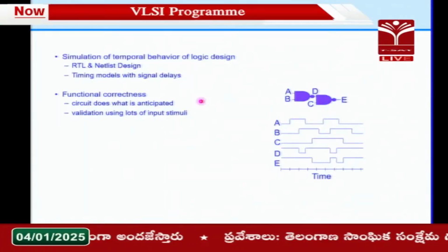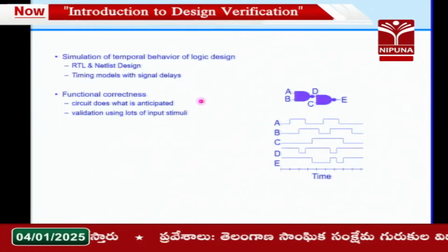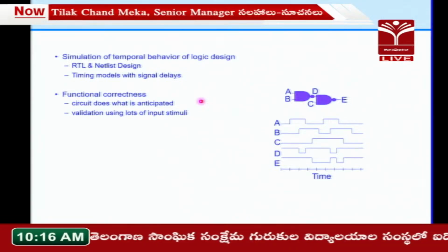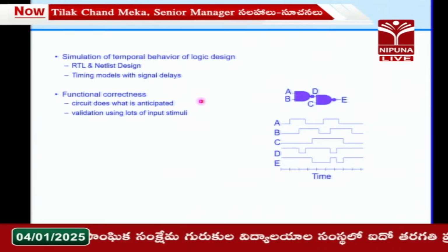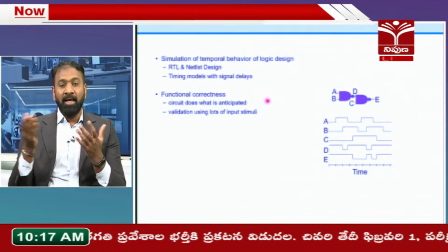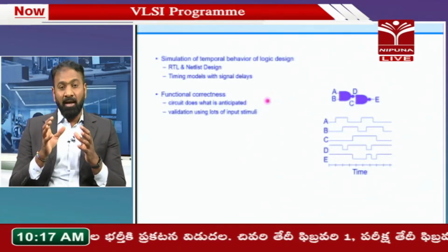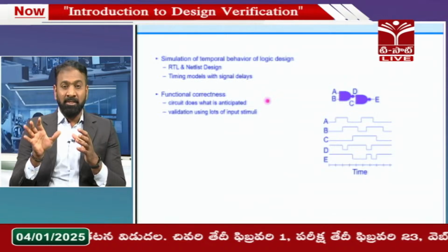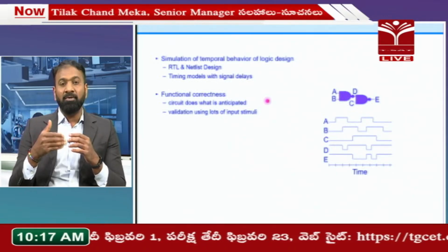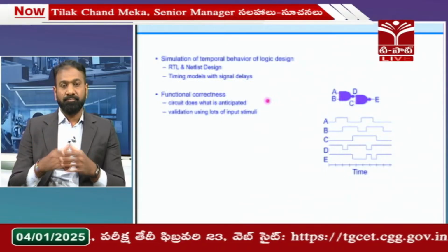Let us take the same example of an adder. If I have to say that my adder is working correctly with all kinds of inputs, I have to apply each kind of input to ensure my adder is fully working. I have to ensure the scenario of 1 and 1 is also captured, because when I add 1 and 1 it results in a sum of 0 and a carry of 1. So, are all the scenarios of your design correctly verified or not? You have to simulate with lots of input stimuli.